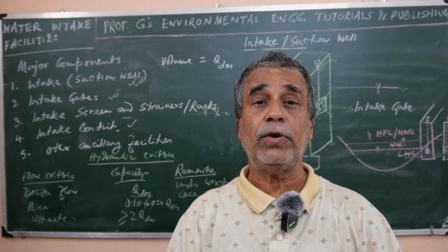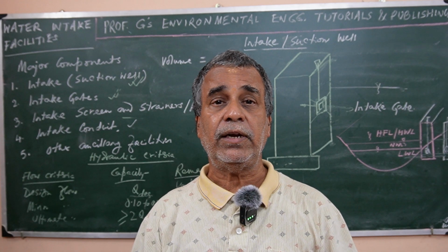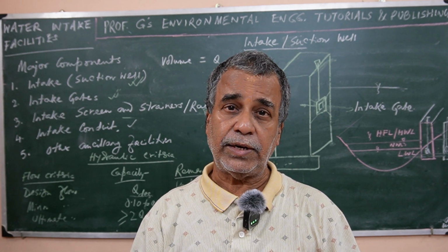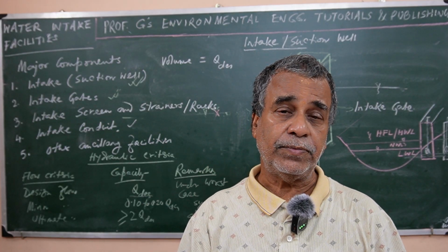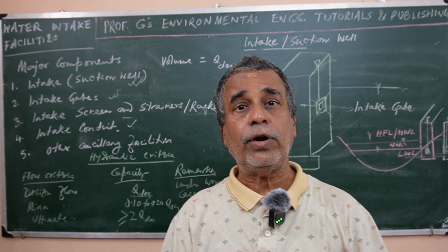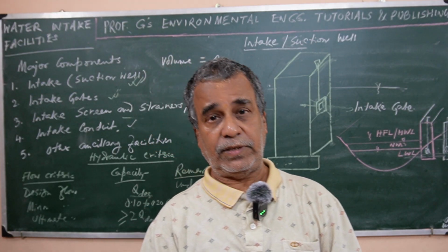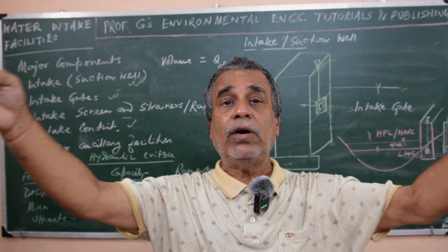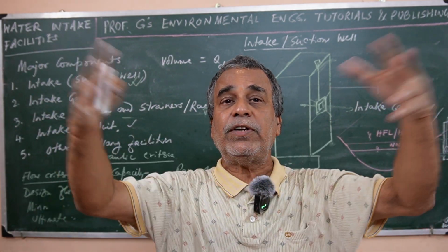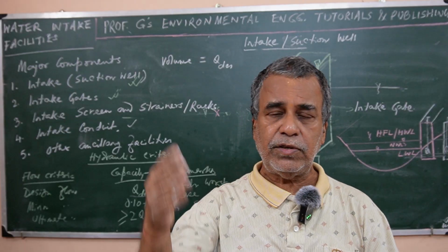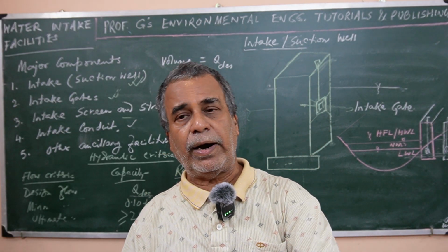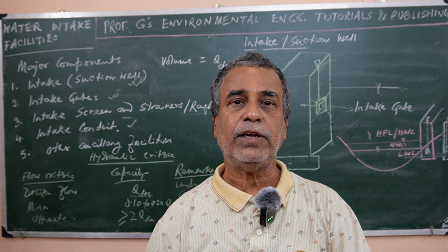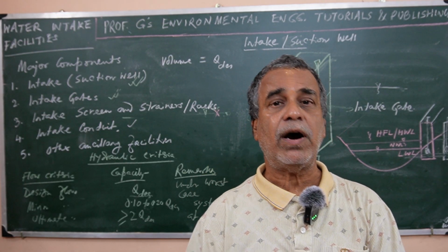By the population projection method, what is going to be the population after 60 years, at the end of the design life? That will be your capacity. So the daily capacity will be your this one, because the town will grow, the population will be increasing. So by a suitable method for population projection, you can forecast the demand.